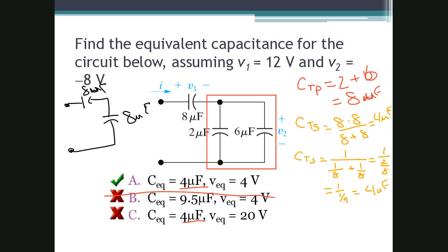So let's go to another color. I'll use green. Okay, so we are given 2 voltages here. The author says that this one is dropping 12 volts, and this capacitor here is dropping minus 8 volts. And so now we can use KVL, because it actually applies here. Kirchhoff's voltage law, where the total voltage is equal to the sum of the individual voltage drops.